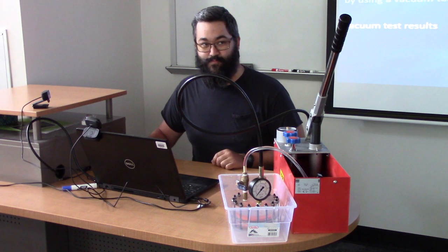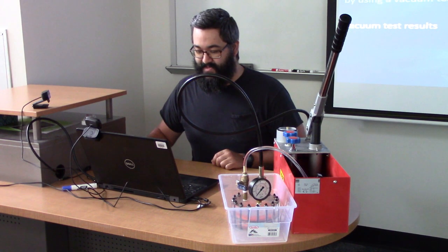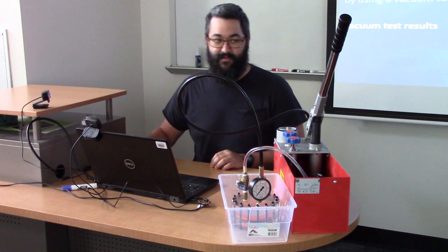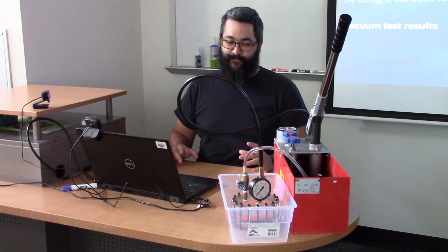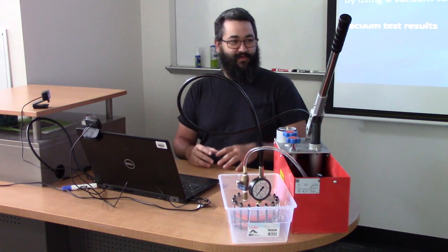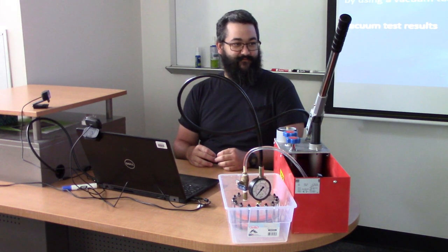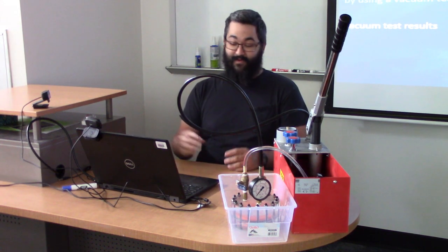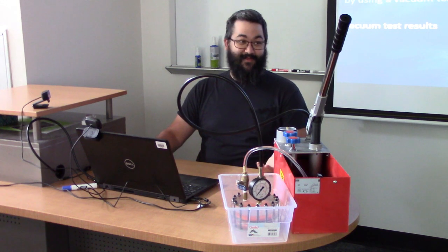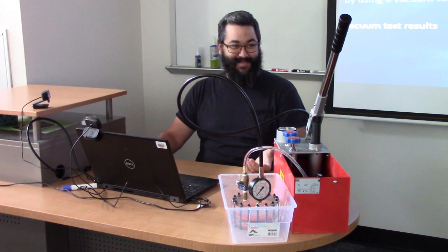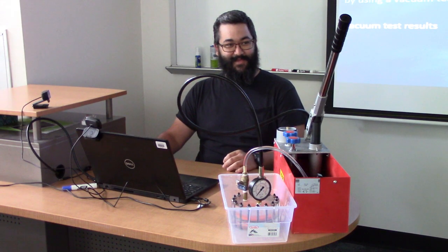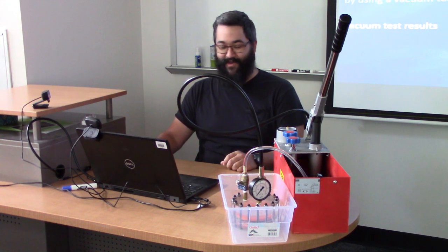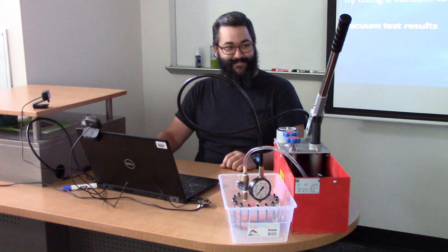Why do you think the 0.2 layer height outperformed the 0.3? From some research that has been done, not by me, but by others, it's kind of weird, because with 0.3, you can assume that the voids are going to be bigger within the layers. But then that would also mean that the 0.15, which is the blue here, should theoretically outperform both of them, but it doesn't. So I'm not actually 100% sure. That's a really good question that probably needs more research done on. Maybe it's porosity.